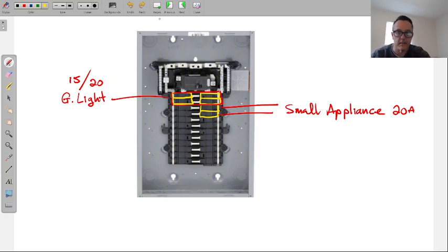Now, to your question, yes, if you have a panel maxed out, nothing else can be done, we've exceeded all the options we have, then yes, you have got to increase the main on that, and it will also require the utility company to bring you a larger conductor size down too. So we need permits for all that. And so what you think will be like a $600 job is going to turn into like a $16,000. Yeah, that around service change like that with the wires, I'll do it for about $3,000 to $4,000.